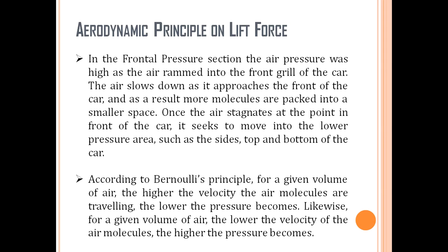Aerodynamic principle on lift force. Okay. In the frontal pressure section, the air pressure was high as the air rammed into the front grille of the car. The air slows down as it approaches the front of the car, and as a result, more molecules are packed into a smaller space. Once the air stagnates at that point in the front of the car, it seeks to move into the lower pressure area, such as the sides, top and bottom of the car.